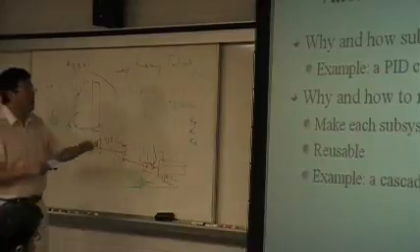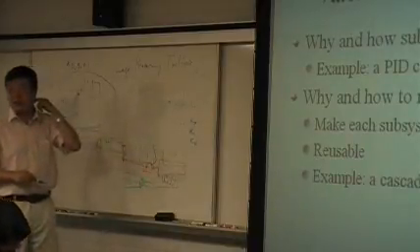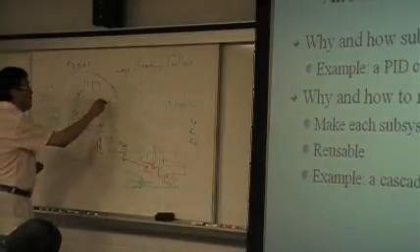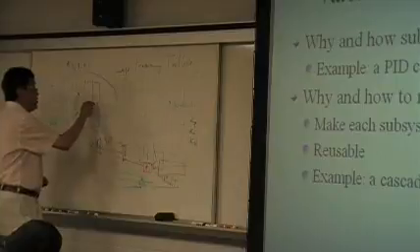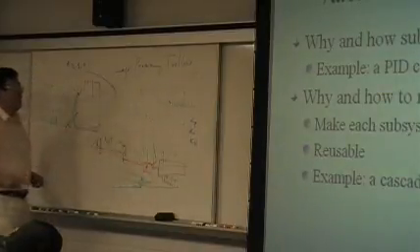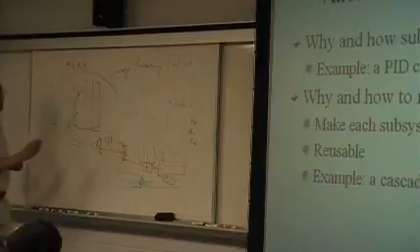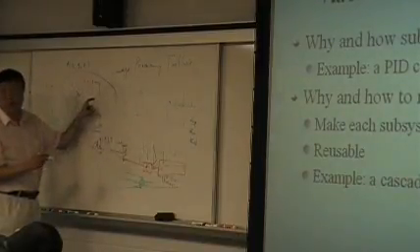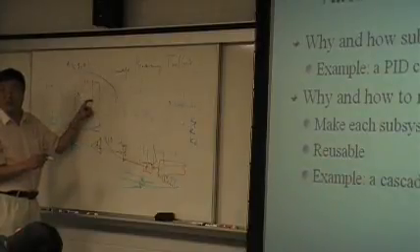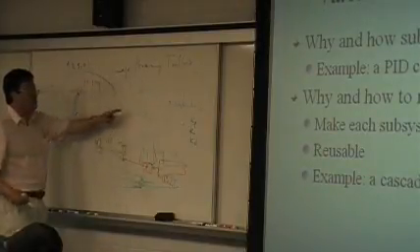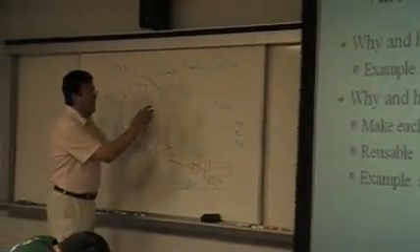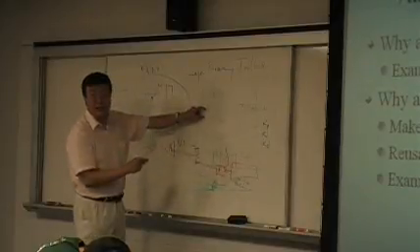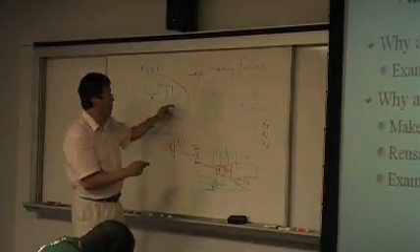You can follow the structure of the mask subsystem and create a block. Next time, when you use a PID controller, you can use the masked PID controller here and here. If you want to change the parameters, you double-click this PID controller, and with the dialog box you can specify them independently, without affecting the other one.